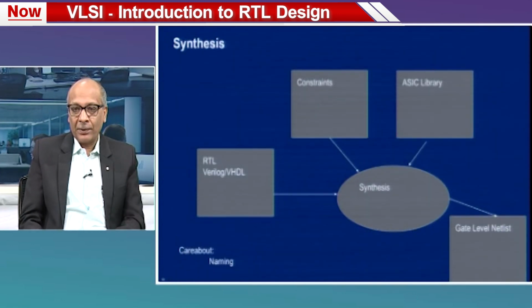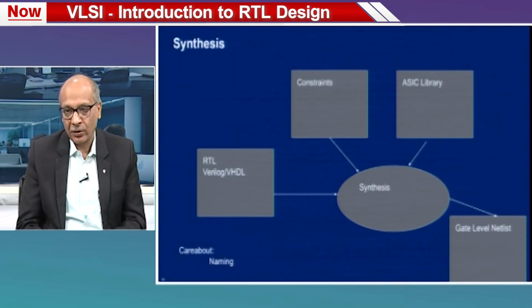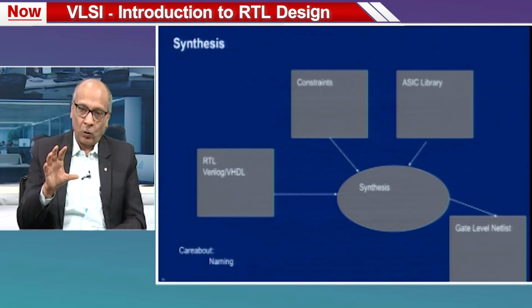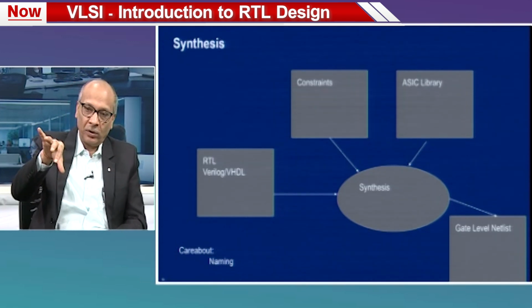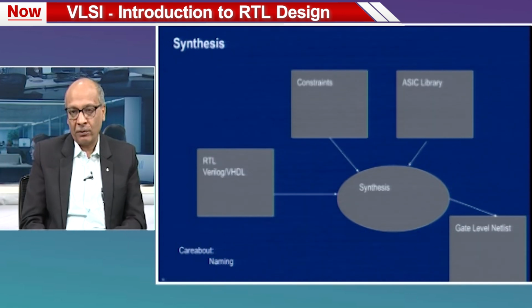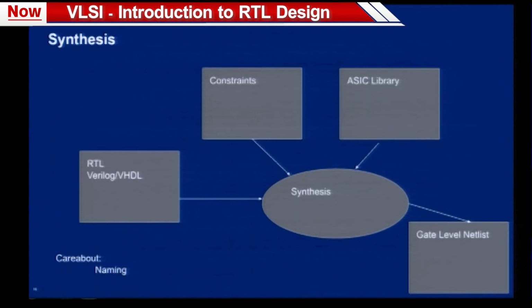We talked multiple times about synthesis. Let us understand what is synthesis. Okay. So, synthesis is a tool where you give the RTL code, okay, and it will give you the gate level netlist. We will talk about few other boxes, right. So, that is a fundamental idea behind the synthesis. Synthesis tool, you feed in an RTL code, be it Verilog or VHDL, and it will give you a gate level netlist. When you talk about gate level netlist, this means the design in terms of digital logic. This design now after synthesis has the flip flops, the AND gate, the OR gate, the MUX, the XOR, and so on.